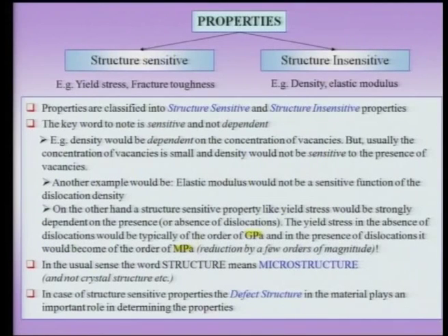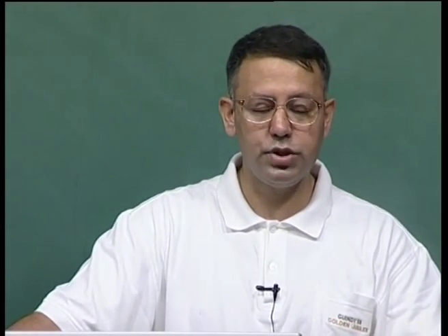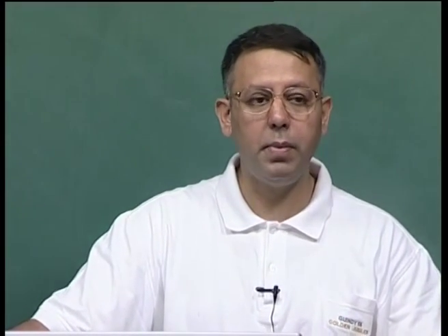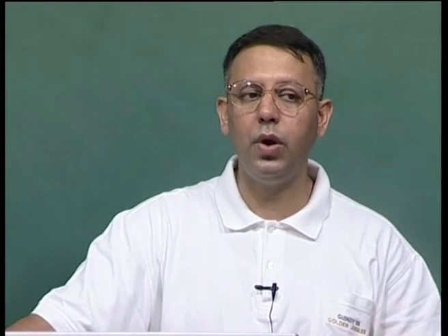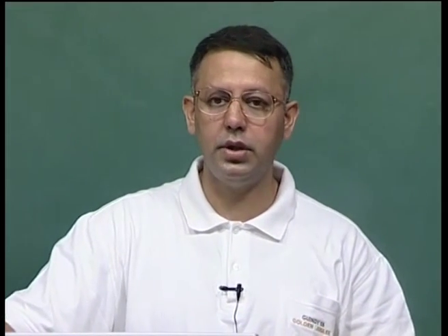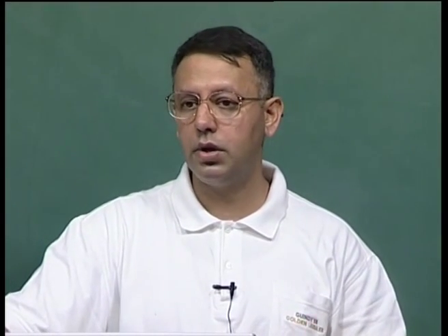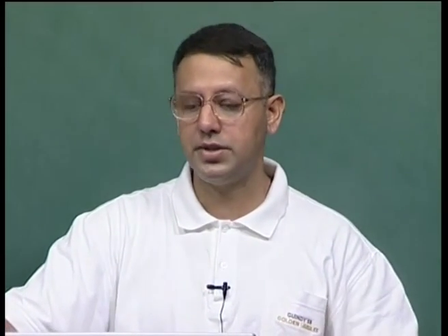Of course, a more philosophical kind of question we can ask is whether these defects are good or bad. It depends on the context. For instance, suppose I am talking about forming a component by plastic deformation, then I want the crystal to be weak, so that I can use a press which is of lower tonnage. Suppose I am talking about forging a crystal, I would use a lower capacity machine. That means I need to have a lesser investment on the capital cost, and the operating cost also will be lower. Therefore, in this context actually dislocations are good, because they give me an easy plastic deformation.